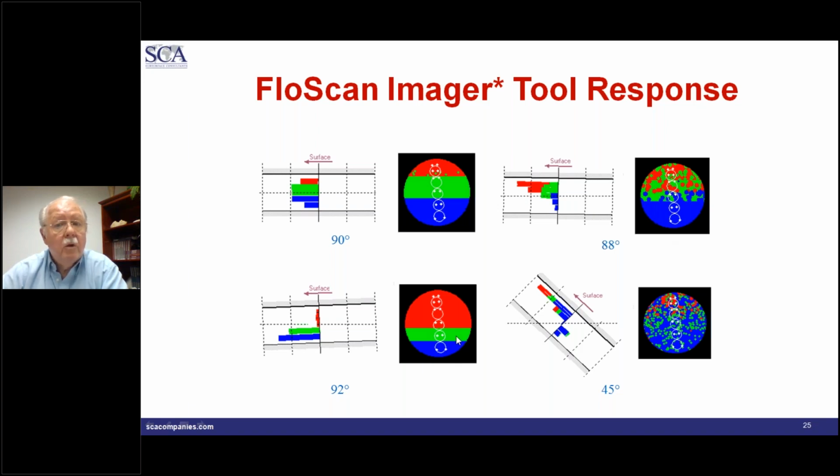the wellbore. Here we have an upflow. I might mention that you see here the light phase moving up very quickly at the high side. Generally, if you have an upflow, that flow can be very violent and slugging. Here we have the classic fallback, 45-degree well. You see the gas phase going up here and oil phases going up, carrying a substantial amount of water with them. What we find on the low side is we find basically water mostly coming back on the low side of the pipe. So here's the fallback phenomenon.